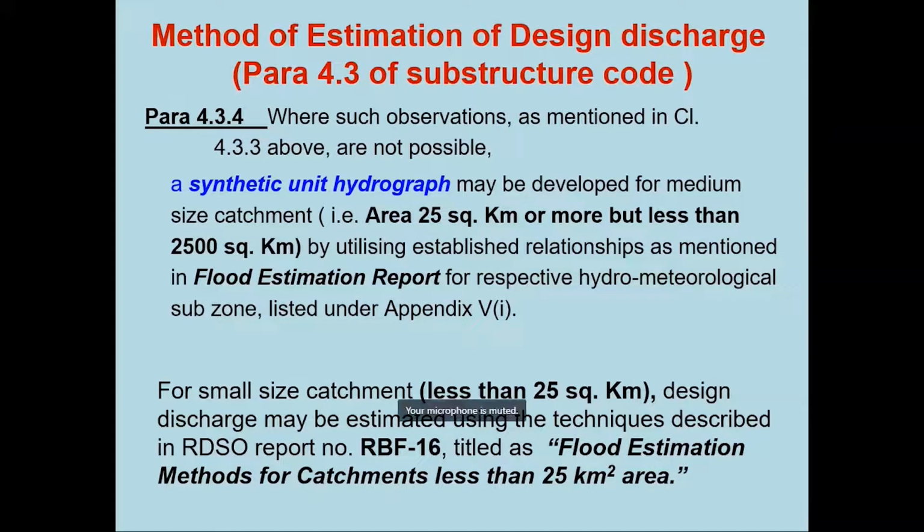So what has been mentioned is that the Central Water Commission, RDSO, IMD have developed some modules, and in those modules empirical relations have been developed based on different rain gauges spread over those areas, where the rainfall and discharge data is almost available for those zones, and a synthetic unit hydrograph has been decided.